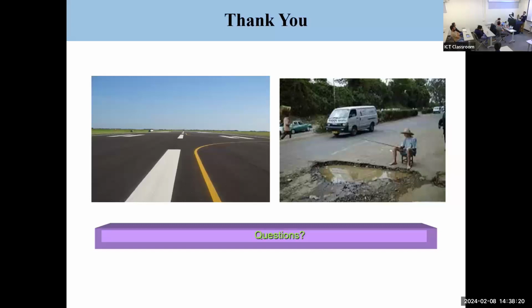The higher the confinement, the less fast it goes to the plastic region. So it has all the components, I think. Now, can you use another yield surface to get those or even better? Most probably yes, but Drucker-Prager has some of the criteria that are important in that matter. Does that answer the question? Yes.